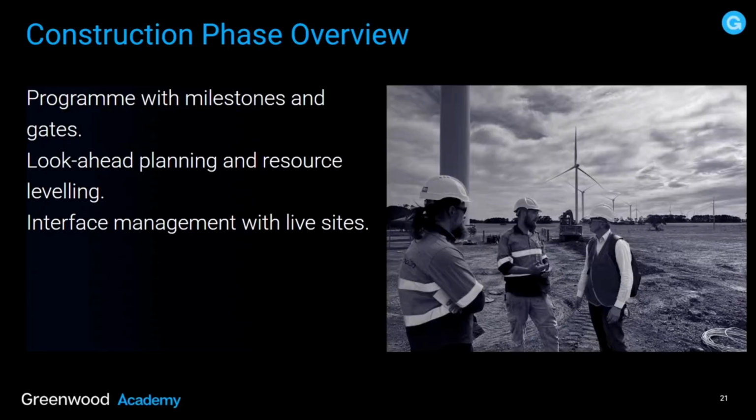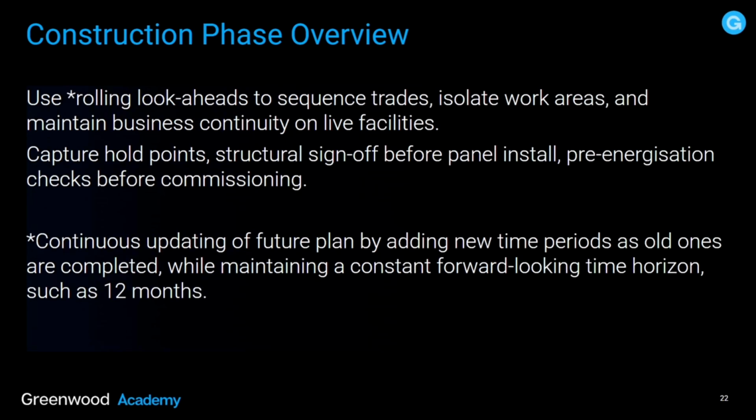Construction phase overview. You have to be looking at things like program with milestones and gates, look-ahead planning and resource leveling, and interface management with live sites. Use rolling look-aheads to sequence trades, isolate work areas, and maintain business continuity on live facilities. Capture hold points: structural sign-off before panel install. Pre-energization checks before commissioning.